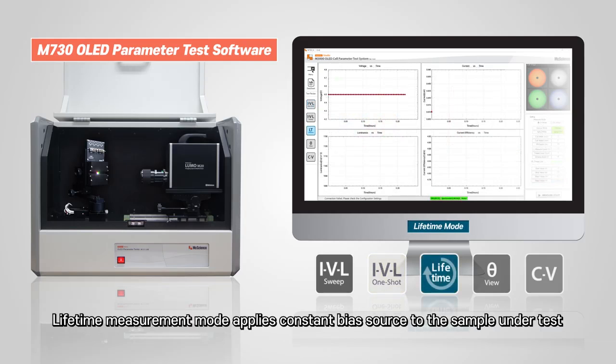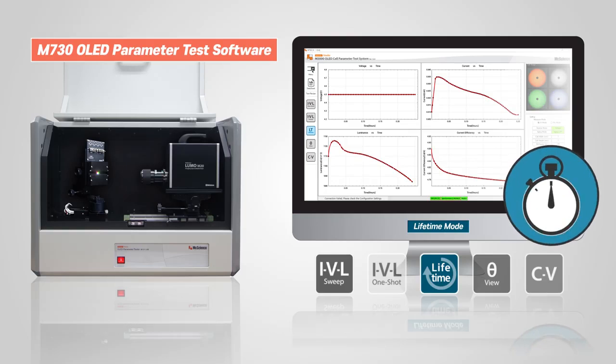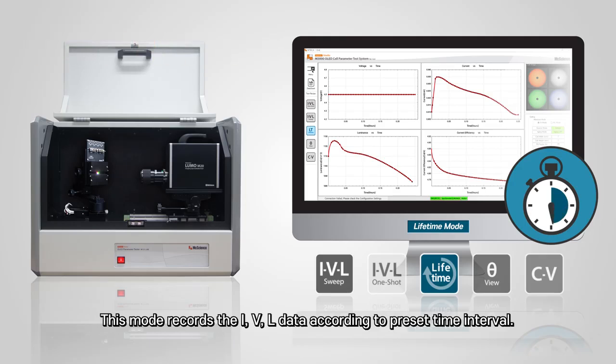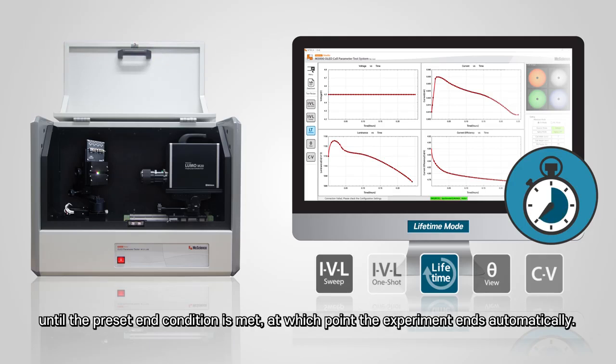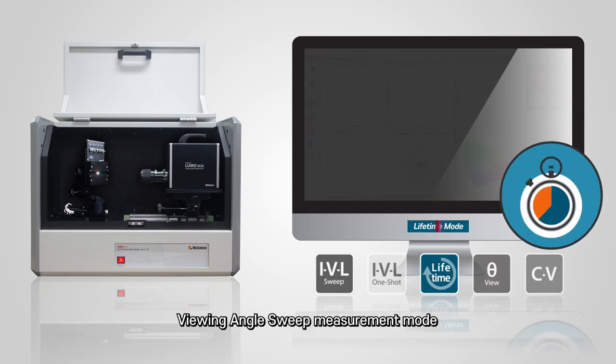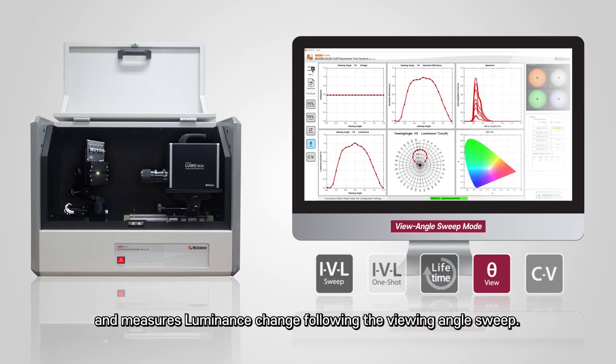Lifetime measurement mode applies a constant bias source to the sample under test, while measuring and recording the changing luminance data over time. This mode records the IVL data according to a preset time interval, until the preset end condition is met, at which point the experiment ends automatically. Viewing angle sweep measurement mode also applies a constant bias source to the sample under test, and measures luminance change following the viewing angle sweep.